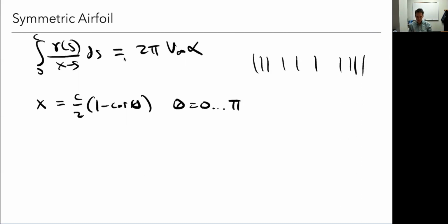This is used a lot for things like airfoils and wings, where let's say on an airfoil, a lot of my change happens at the front and the back. So I want to tightly discretize. Same with a wing, a lot of things will happen at the wing tips, and so I want to change my discretization. That's not why we're doing it here. That's just, by the way, something we'll also do later. When we go to evaluate wings later, we're going to use the same transformation.